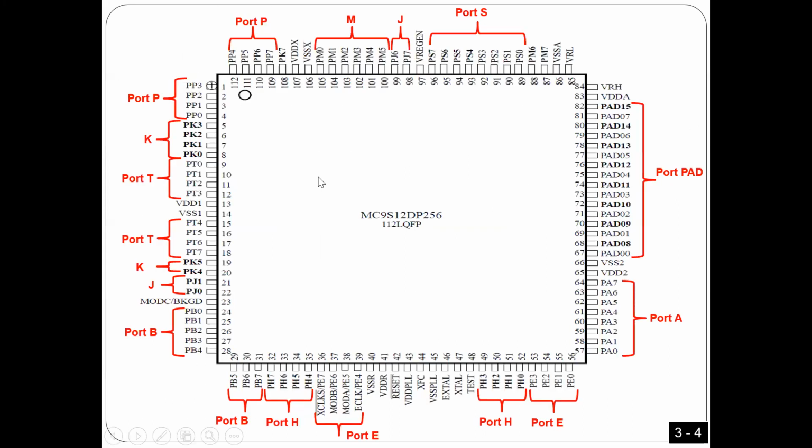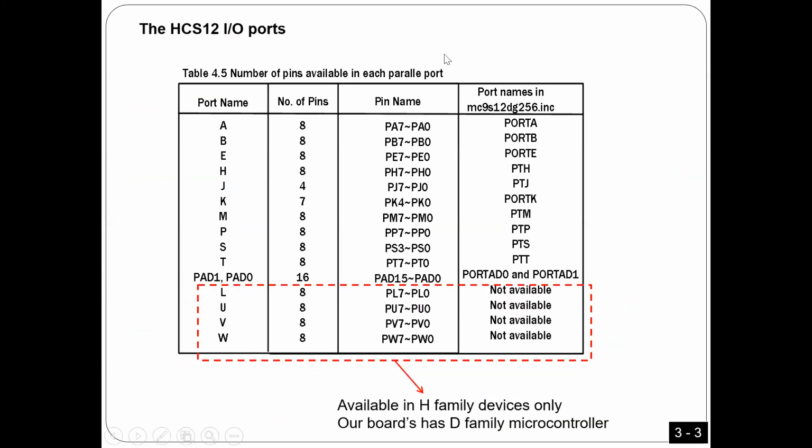So here, the way we define the English names in this file is, for port A, we use PORTA. This is how it is defined. So you can just use the word PORTA, and PORTA is going to be replaced by the address. Again, any instruction we used before for a memory location, you can also use it with this one.